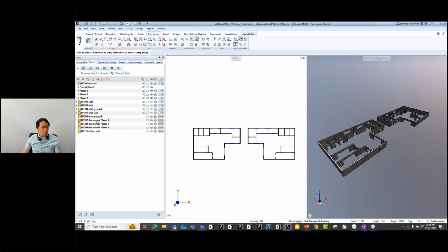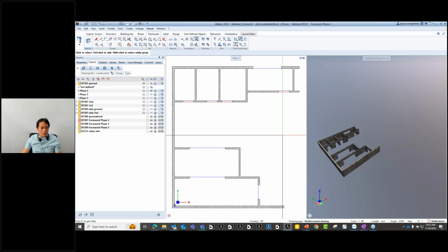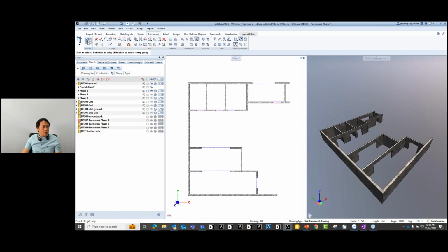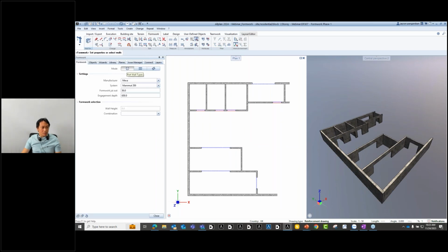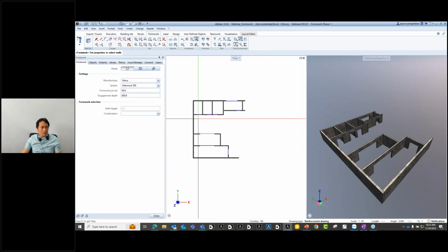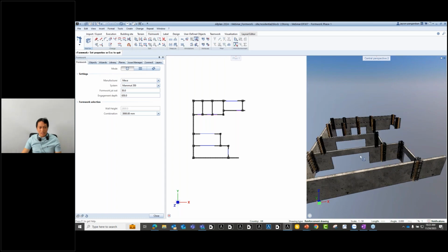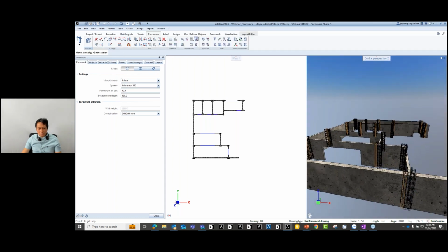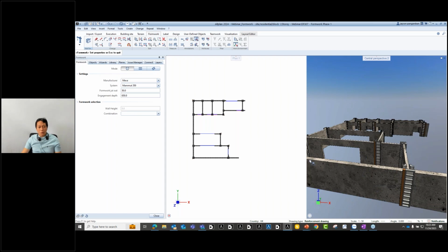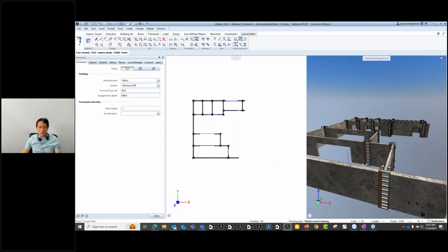So for the formwork, now I can activate, let's say, first the phase one. So we just focus on phase one. And then using this function, wall forming, we have this part wall type. So basically, when you see this, I can just say highlight. Okay, so I can see that it automatically gives you your formwork for your corner parts. So it's very easy to use.